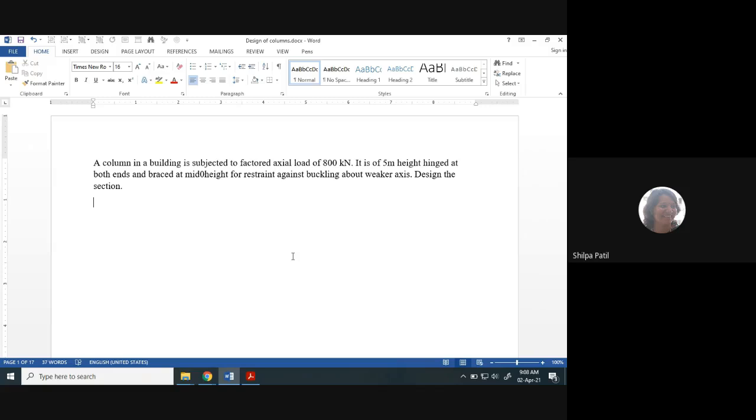Based on FCD and area, calculate PD and compare that value with the force acting in the member. Depending upon that, you write down whether the given section is sufficient to resist the force, or the section is not safe and is required to be revised. I have purposely not considered problems based on capacity, because the process is similar; only the initial steps will change. So we will now solve the design problem directly.